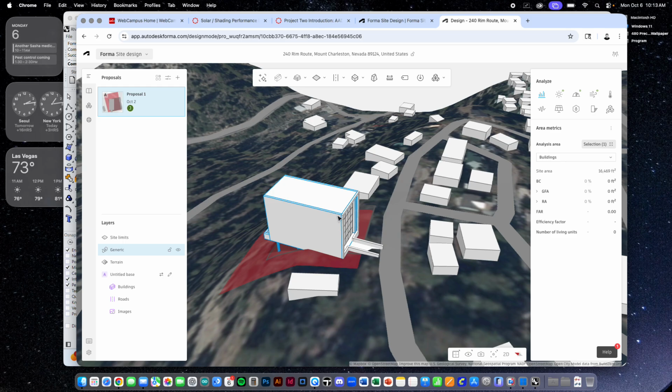The idea being that with a desert building, we can control the sunlight coming from the south. The north we can glaze. The east and west is where we really want to control things because that's where the sun's lower in the sky. We want to minimize glare and things like that. Just do things very specifically. And I have some custom windows that I've made for you guys, a custom family. I'll show you how you can modify the types in Revit to do that.